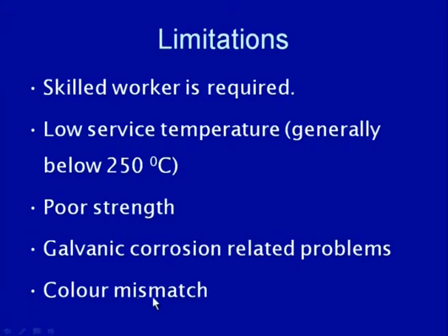Color mismatch can be another limitation related to braze welding, because the braze filler material sometimes offers a different color from conventional base materials like steels, and therefore, there can be a mismatch which can adversely affect the aesthetic value of the product which is being joined by braze welding.